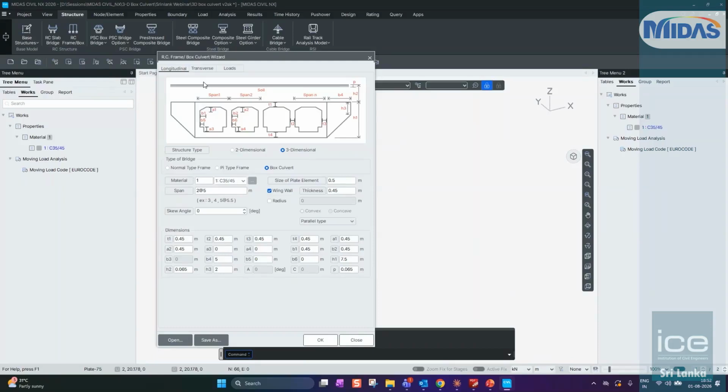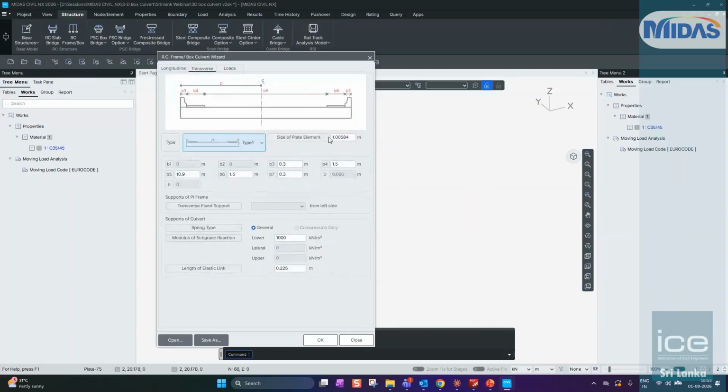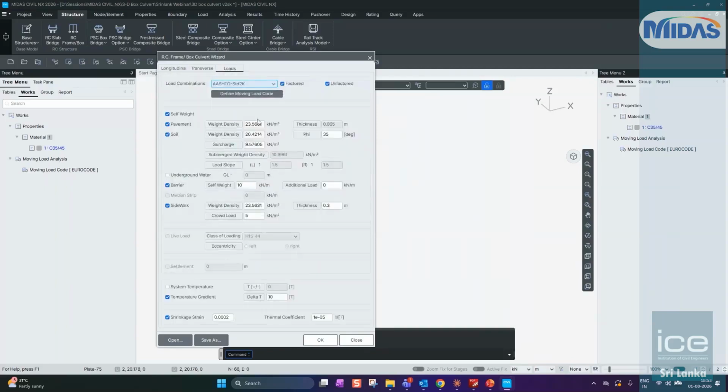Say for example, you think that the pavement might not be removed, and they might go for 2 to 3 times the surface coating when the pavement gets damaged, right? Of course after that you'll see a lot more cracks. So in that case the removal of pavement and surface coat itself is beneficial. Then the pavement will again be applied to the RCC level, right? But if you expect that they can go for multiple surface coatings on those culverts, please do account for that additional pavement loading thickness. Currently I'm using 65 thickness, and I'll go ahead with that.